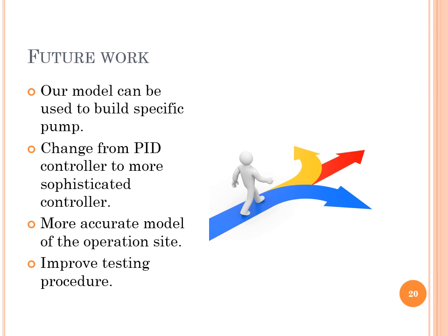More work can be done, like changing the PID controller into a more sophisticated controller, like an MPC controller that can track multiple inputs for the regulation of the flow. Also, a more accurate model of the bladder should be added to replicate the physiological response of a pressure change, to help tune the model to make it more reliable. The testing procedure can be enhanced to include noises and errors to see how the system reacts and adjusts to adapt to the situation and keep the patient safe in any case.